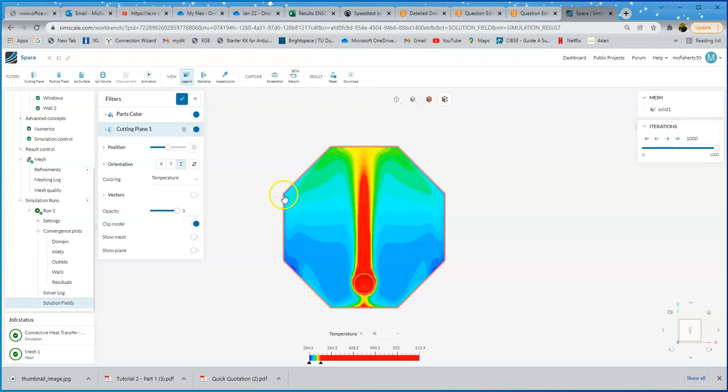So along the roof here, and particularly on this top panel, we're seeing big temperature differences between the inside and the outside. So I would assume the bulk of the heat transfer, the most intense heat transfer, would be out through the roof and these areas here, but also out through the bottom as well.